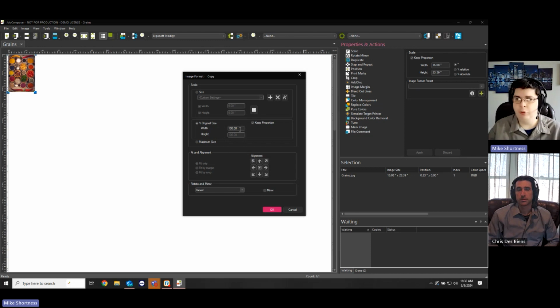Illustrator has a limitation where you're limited to a certain size, but if you need something to be 500 inches wide, you can design it at 100 inches wide, which is a fifth scale, and then you can set this original size to be 500% scale, which would then make your final product be 100% of what it needs to be. So that's what this original size is used for.